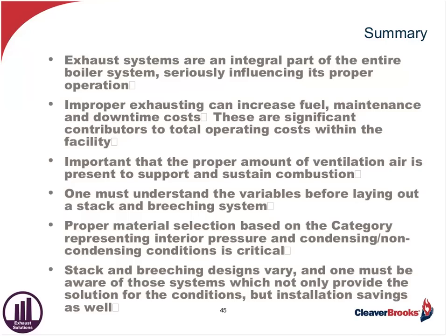Okay, Steve, how does sealed combustion factor into the exhaust calculations? Do you want to take that, Chuck? Sealed combustion. In sealed combustion, of course, what you've got is air being ducted into the burner itself, and then you've got your vent going out in a separate system. Many times that ducted air, as far as secondary air for combustion, is PVC pipe. Do you want to comment on that at all?